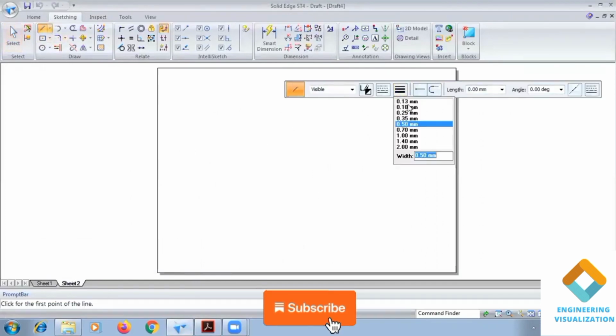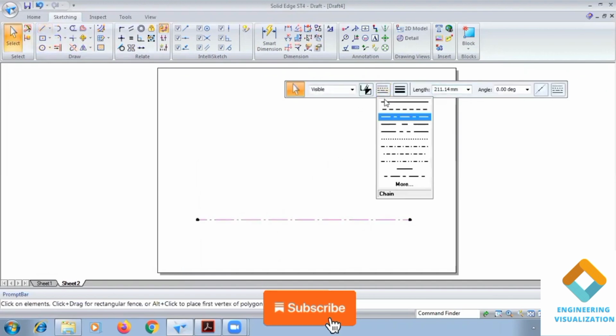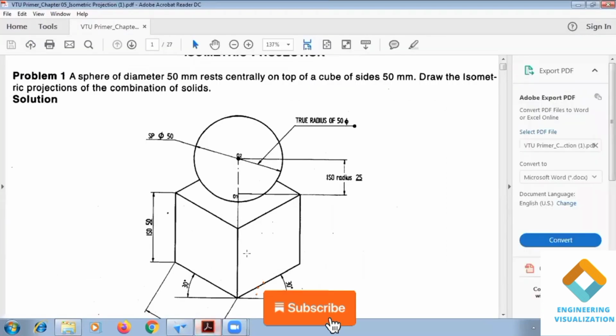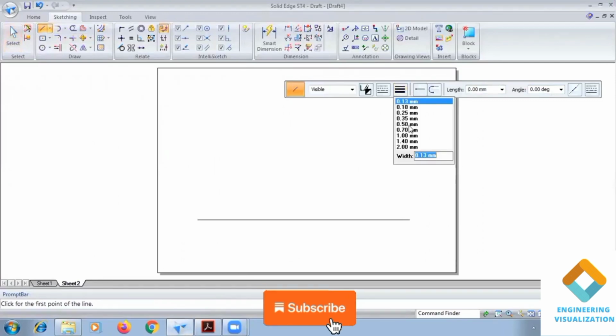So first I'll be drawing a reference line. Please follow step by step, and you will be able to understand the problem clearly and easily. Okay, so the reference line is drawn. Here we need to construct the cube first. This cube has sides of 50 mm, so we need to consider a 50 mm box. So please consider the angles.